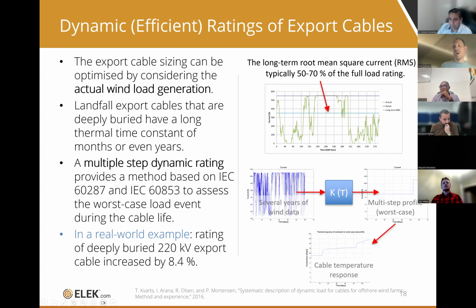The dynamic rating of these export cables is really quite important. So it's not a good idea to consider that the export cables are operating at full continuous rating all the time. Because the export cable is buried, there are large or long time constants. There is high thermal inertia for these deeply buried cables. We can take advantage of that.